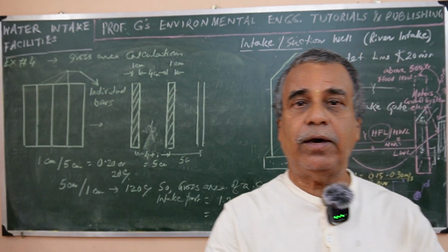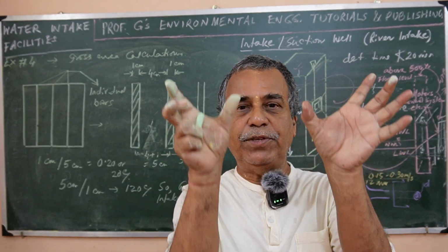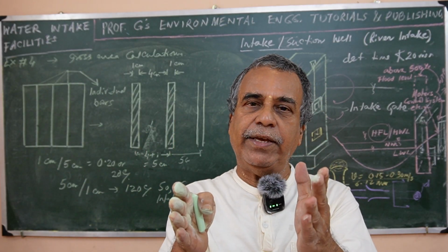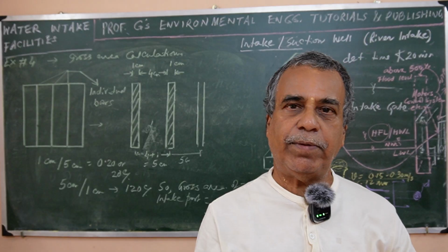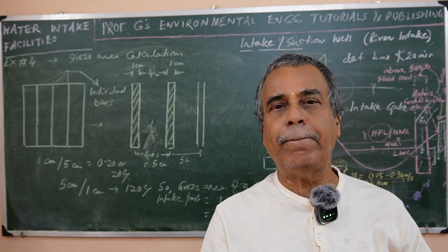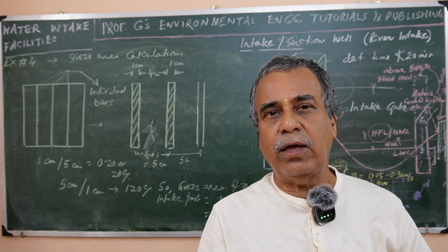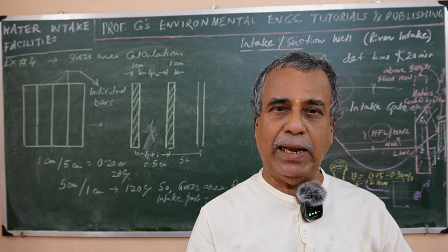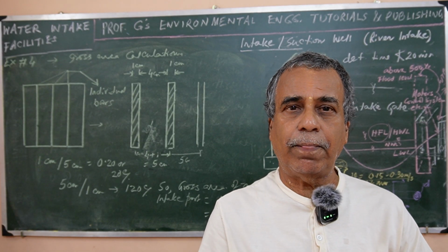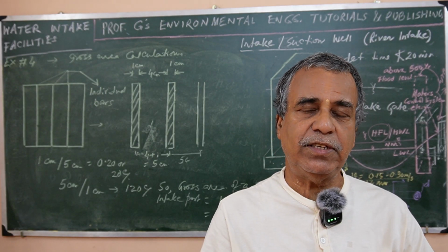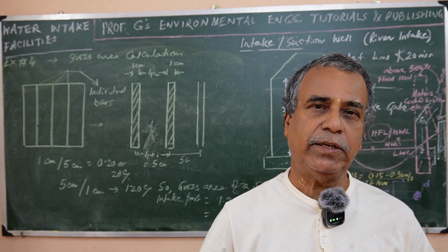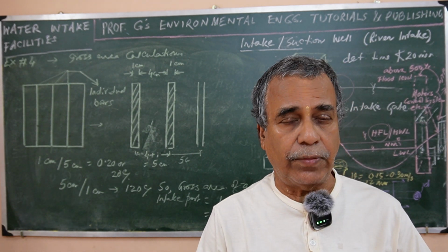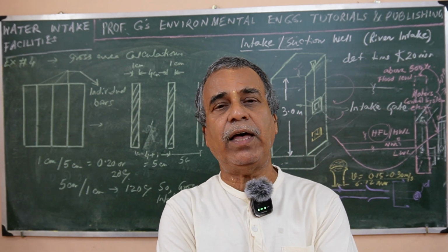If you make a bar type configuration, the opening area you have already calculated directly, using the minimum velocity to be allowed through it on a net area basis. We calculated the net area, the opening area, earlier in example 3.